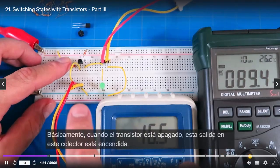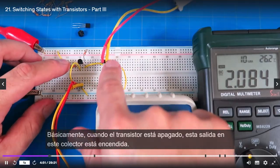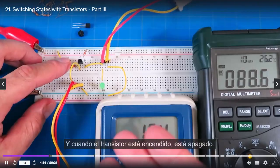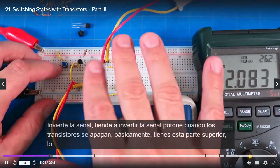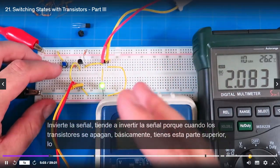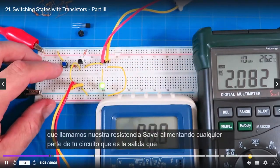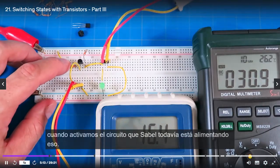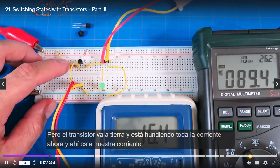So basically, when the transistor's off, the output at this collector is on, and when the transistor is on, it's off. This is why this is called a common emitter configuration. It tends to invert the signal, because when the transistor is off, you basically have this top resistor, what we call R sub L, feeding whatever part of your circuit is the output. Then when we turn the transistor on, R sub L is still feeding it, but the transistor is going to ground and sinking all the current now, and there's our current.